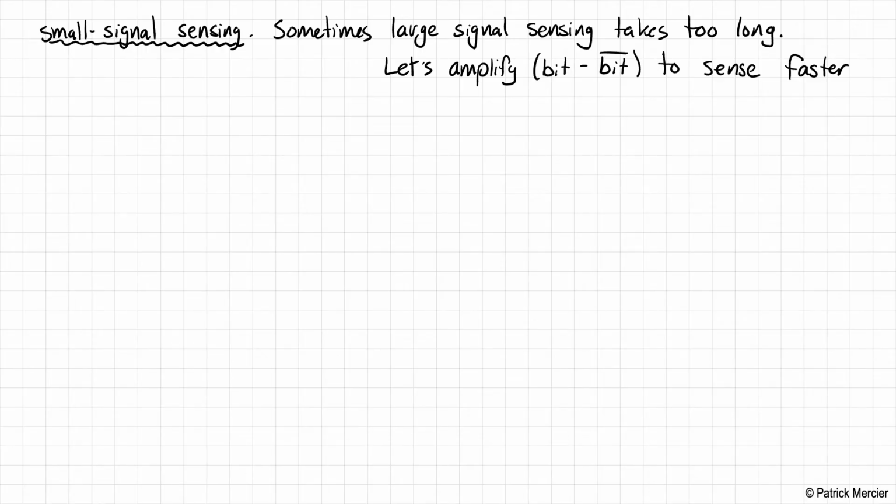Okay, so it turns out this is where this concept of a sense amplifier comes in. Again, I'm going to be a little vertically compressed for space here, although I'll try and do a little bit better job this time. So let's imagine we have our pre-charged circuits up here. This is connected to Phi2 bar. And let's imagine that we have our first SRAM cell in here.